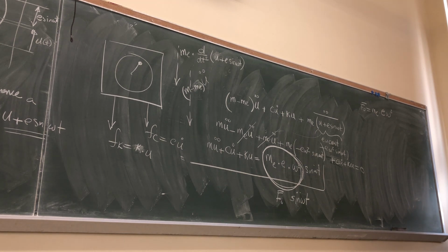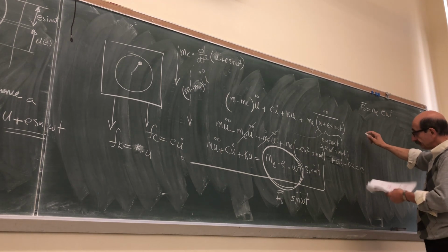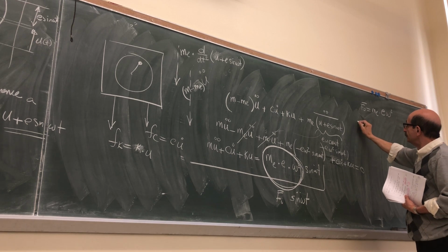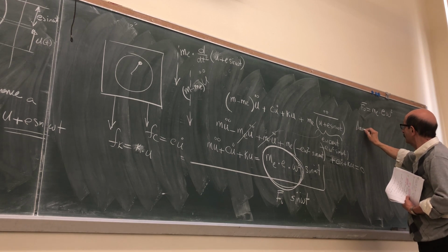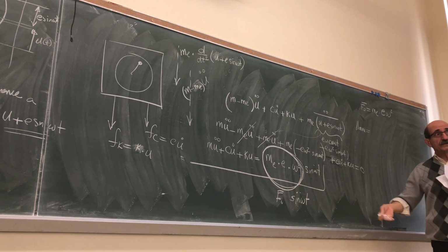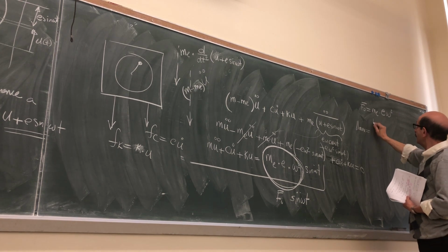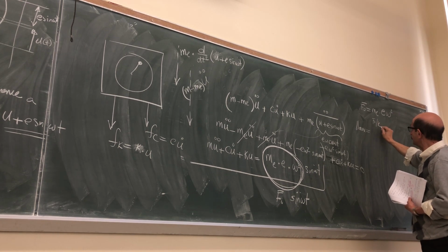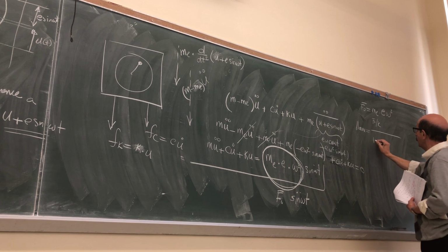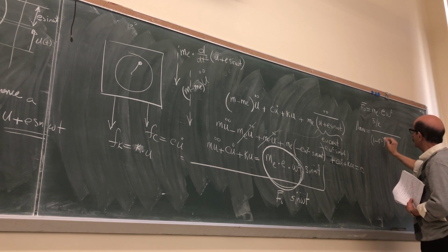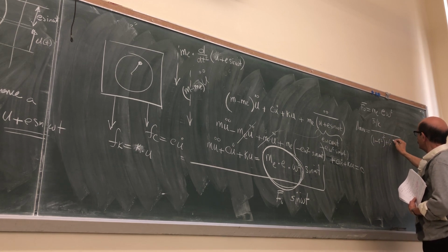You see that then the U max for the steady state response is what? F0 over K divided by the square root of 1 minus r squared squared plus 2 zeta r squared, right?